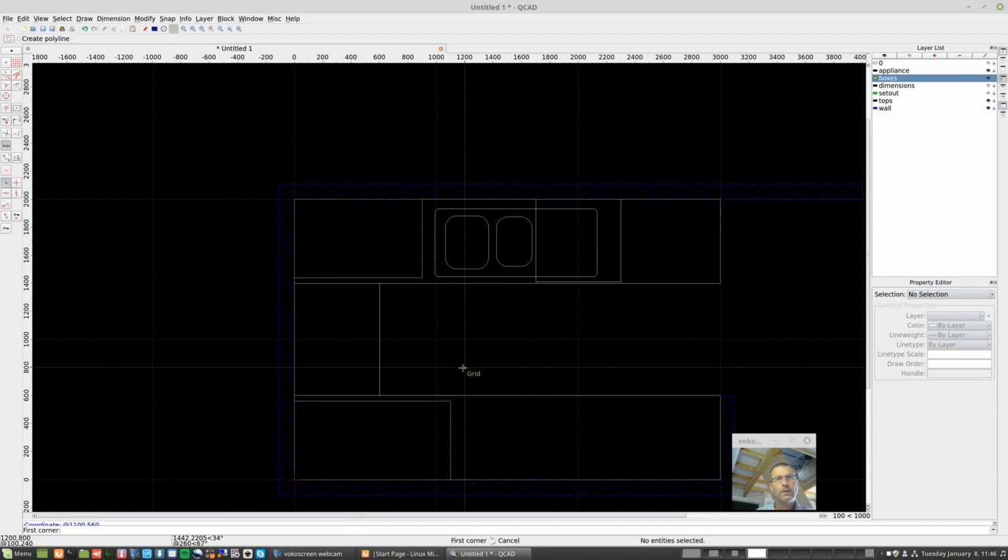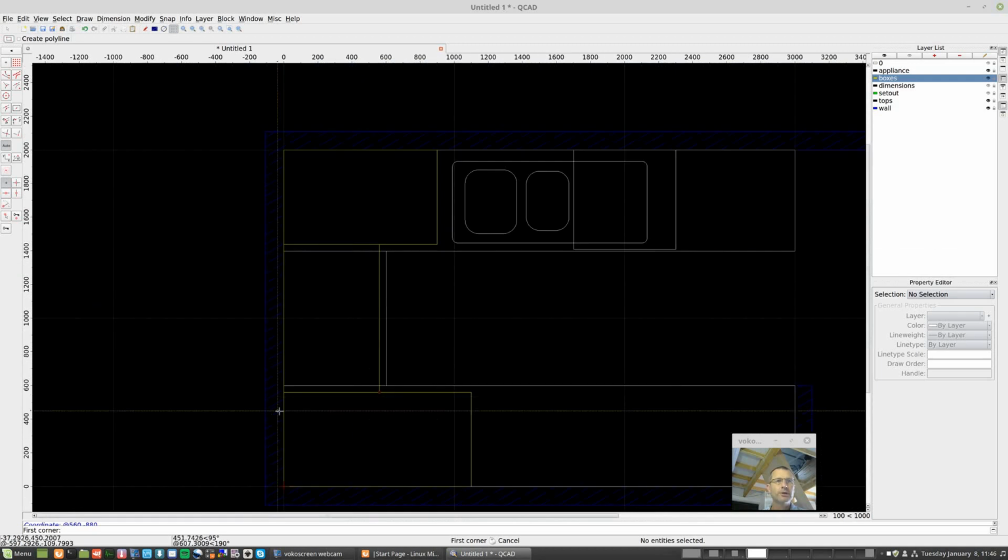Okay, so that's happened. Now we need to have some sort of access to doors, etc., or maybe one of these magic corners, etc., but let's just keep rolling with this. From there to there, which is minus 880, so I'll go space at 560, comma, minus 880, enter. So let's say we've got those, they're the sort of box sizes we could have. Now we can put an upright in the center here, but I'm going to do something a little bit different.